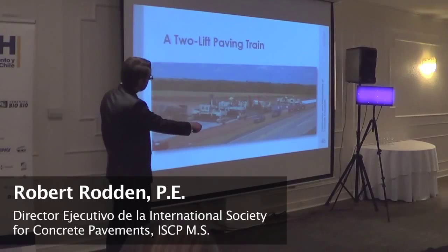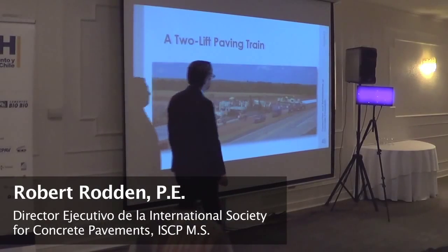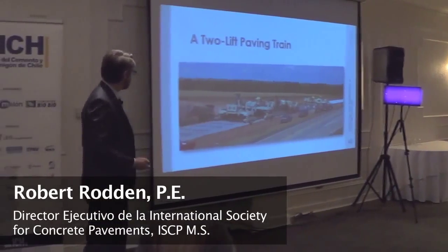So they have one placer spreader, one slip, two slip. This one has the rocket launchers on it, so I can see they're paving three lanes wide because they have two of those across that width. So they're building three slabs wide. And they got texture cure behind that.